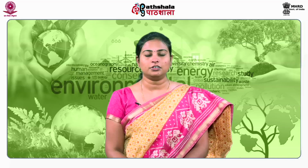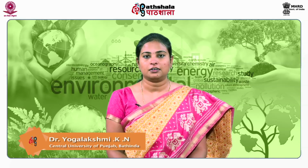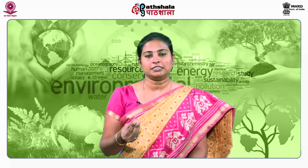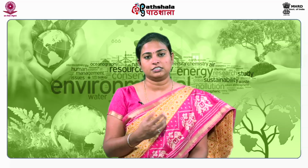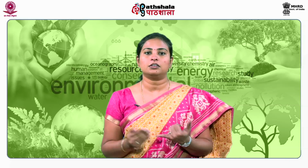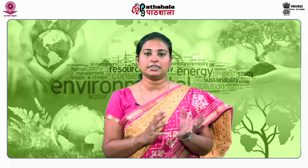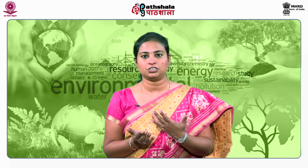Now, to summarize this module, we have studied what a landfill is. We discussed a basic definition of a landfill, and we discussed controlled and uncontrolled dumping. Controlled dumping is also called landfilling. We discussed the different layers that are present in landfills. Then we discussed leachate, which is a watery liquid that oozes out from the waste material during its degradation process. We also discussed how leachate is generated, the composition of landfill leachate, the factors that influence the quantity as well as the composition of leachate generation, and how to estimate the landfill leachate generation in a particular landfill.